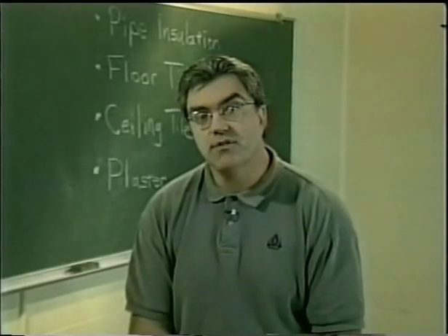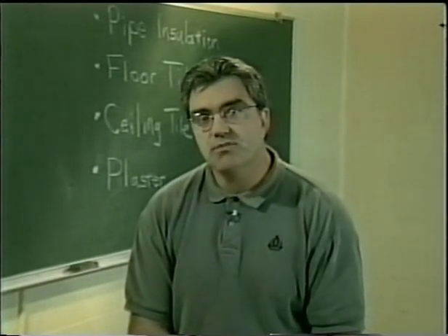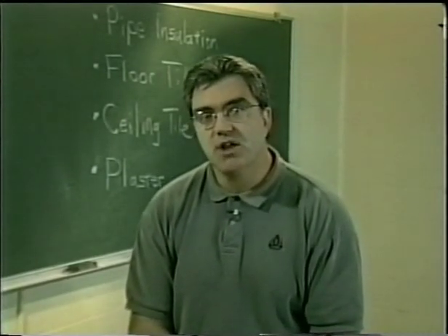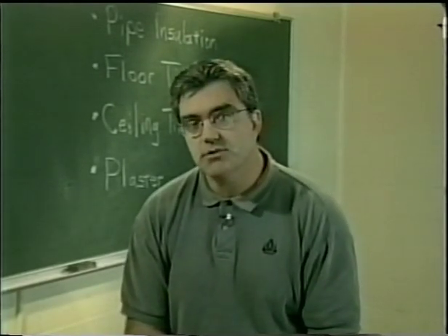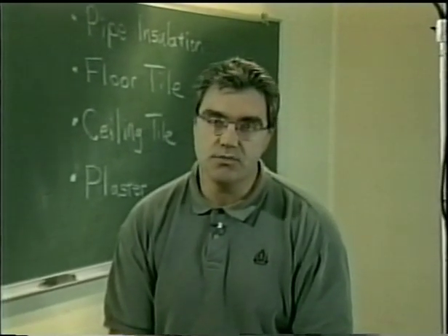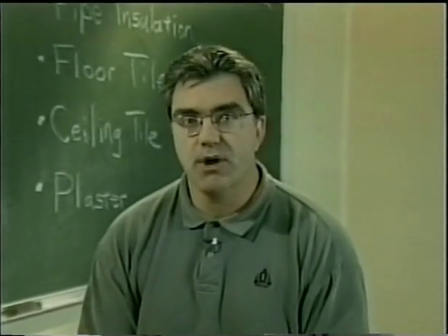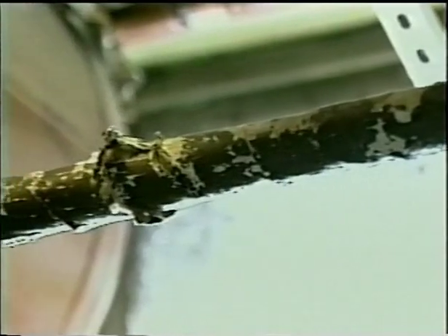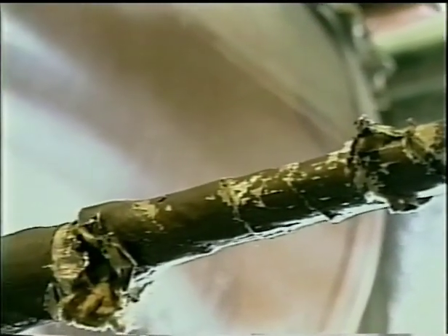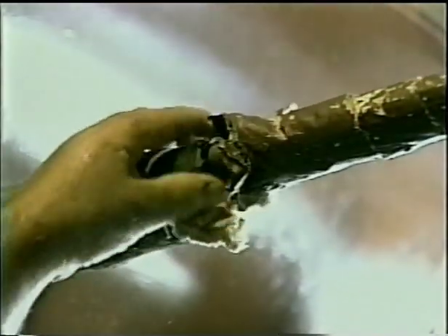Welcome to the second portion of our Asbestos Awareness program. In the first segment, we looked at asbestos, its history, its health effects, and its regulation. Let's turn our attention now to identifying asbestos on building systems, taking a look at when it's hazardous and some proper work practices. The most common way for asbestos fibers to enter the body is through breathing. In fact, asbestos-containing material is not generally considered to be harmful unless it is releasing dust or fibers into the air where they can be inhaled or ingested.